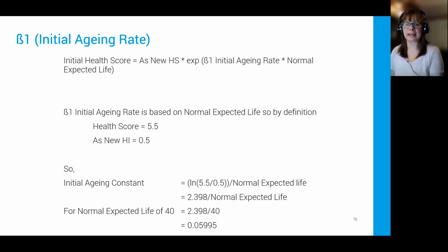And then if you inspect them and they come out good, so there's nothing wrong with them, then they sort of get capped at 5.5. But if you inspect them and there's some condition issues, then the health index would rise. And we use the initial health score as a multiplier. So we start multiplying that up, so you get a higher health score for those assets that are in worse condition.